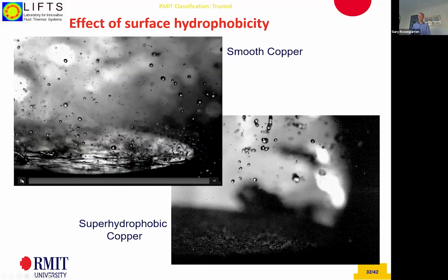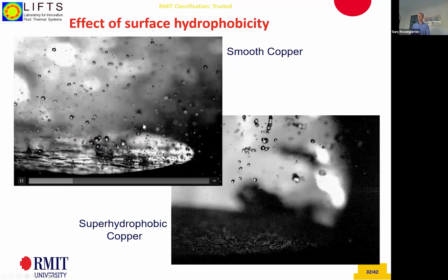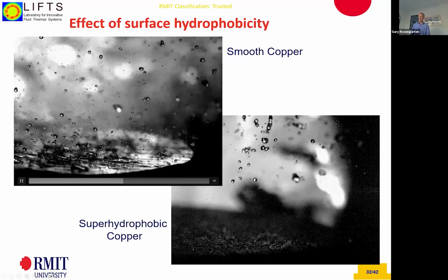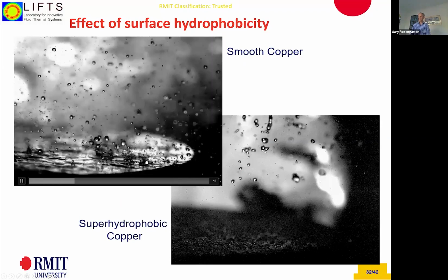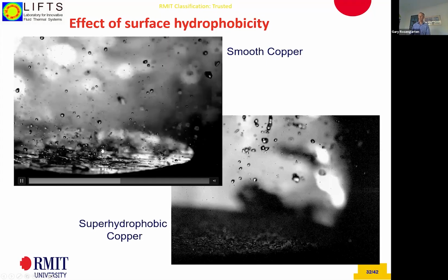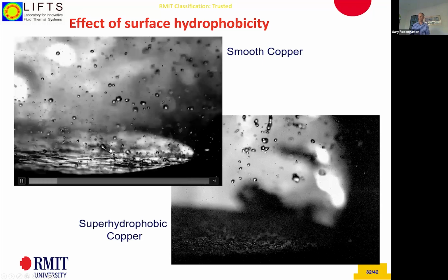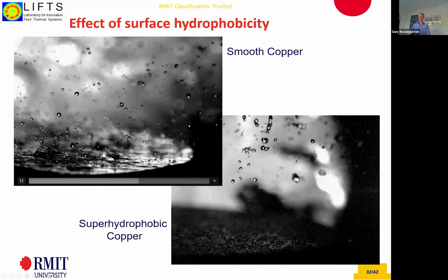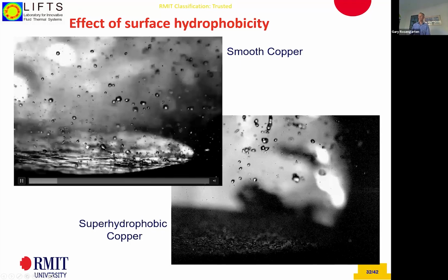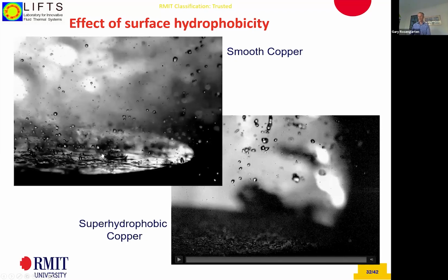If you look at the differences here, this is just a smooth copper surface, we've zoomed up, and you can see here the droplets are hitting a mixture of, sometimes the surface is being cleared, sometimes this is not even boiling. There's no boiling associated with this. It's just non-boiling, below the saturation temperature. But you've got a lot of things happening here, droplets crowning on the liquid film, some droplets interacting with others coming in. But most of the time, it's not really hitting a surface.